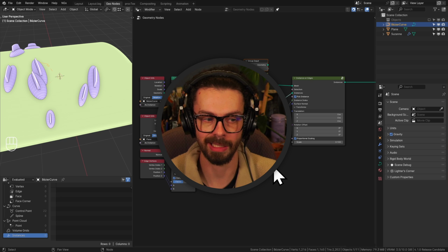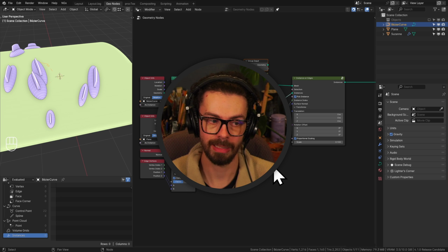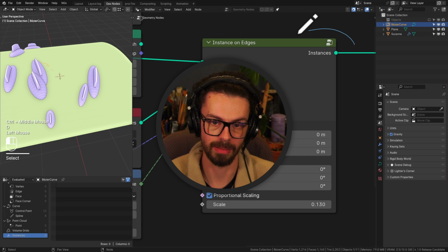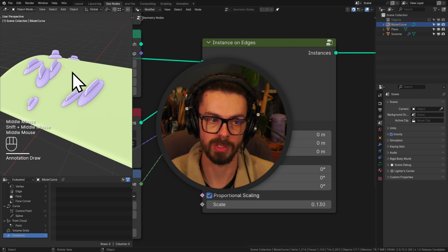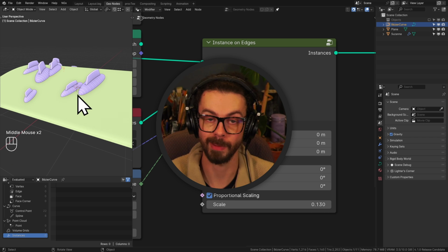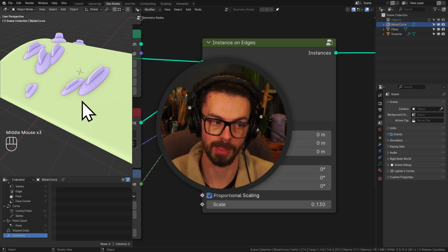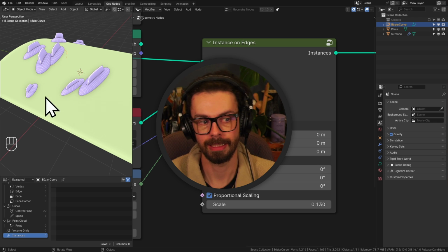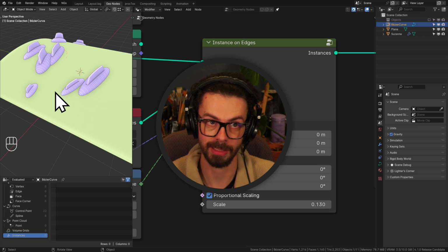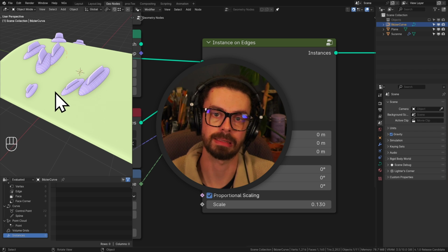You're basically enabling yourself to put anything anywhere, and doing it this way, we're keeping this as instances, right? These are still instances. So no matter how many you have, it'll be super lightweight for you to render, especially with Cycles, and just generally processing them will be fairly straightforward. And because we're doing non-linear scaling and fun little transform tricks, we're able to get a system which is very robust and flexible, even though it's still an instance.